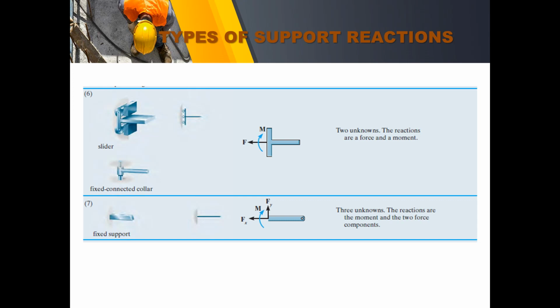We also have here the slider. So the slider will restrain the rotation as well as the horizontal force. And the last support is the fixed support, wherein all of the forces will be restrained in the support, the vertical, the horizontal, and the rotation.